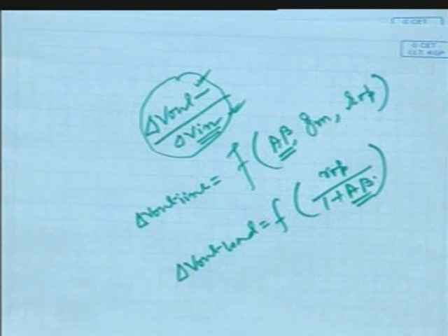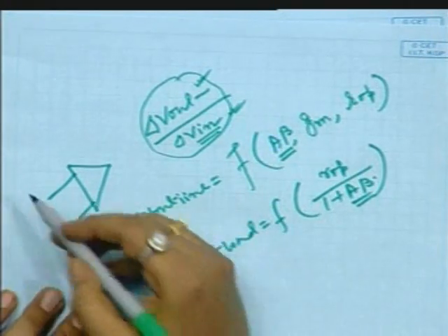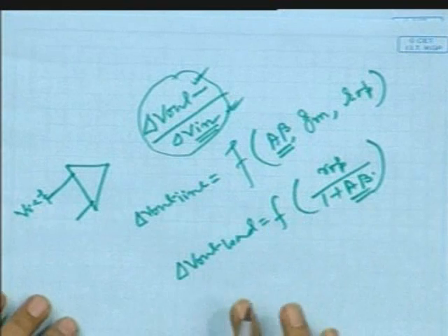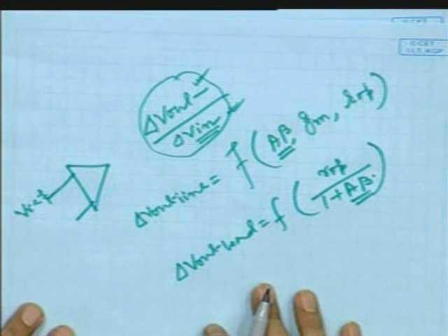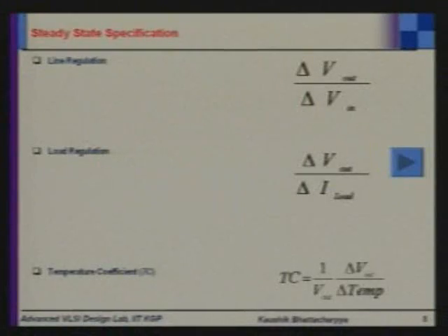Now, temperature coefficient. We have seen that in the two terminals of the LDO, one terminal is connected with the reference voltage Vref. I think you all have studied band gap reference. The reference voltage is provided through a band gap reference, and utmost care should be taken to make it temperature independent and supply independent. But sometimes, due to a small change of temperature, the reference voltage may vary, and due to this temperature variation, the output voltage will also be affected, and this is given by this expression Tc equal to this.